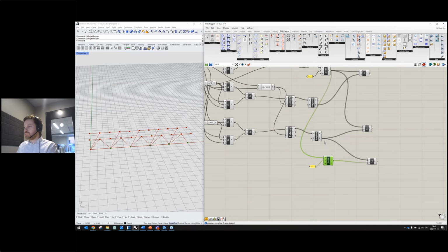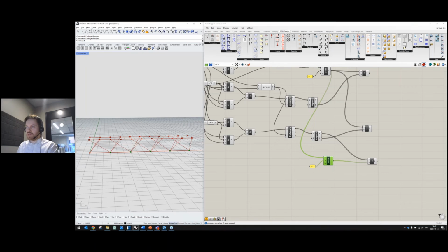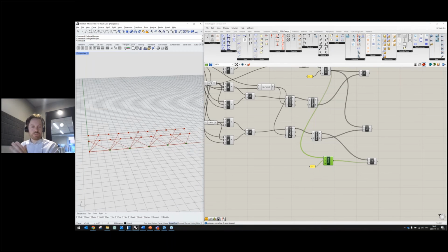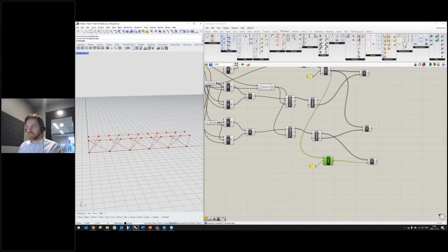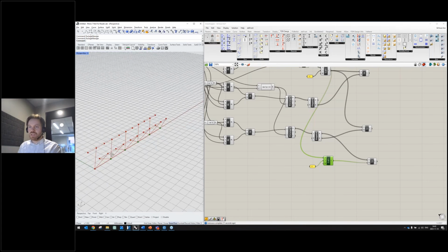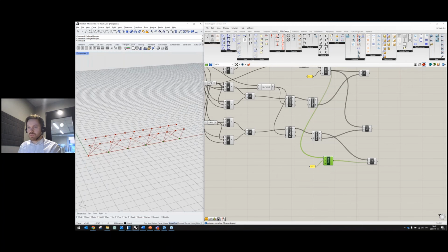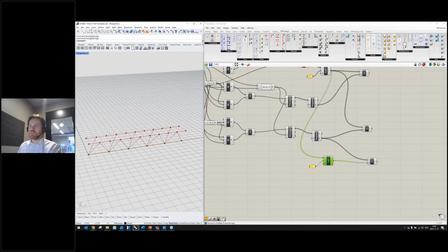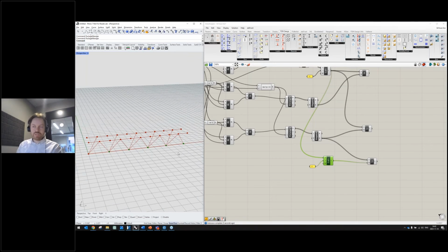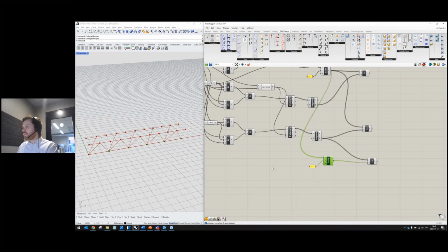points. So if you make a mistake, if you connect it the wrong way, you will get this instant feedback in the 3D view. And this is what's great about Grasshopper and Rhino. You get this instant feedback, so you can try out yourself and see what you can understand, like, okay, I'm connecting the wrong point here. I'm connecting this point, and it should be the second point, and I can find that over here at B, like this. Okay, so getting this instant visual feedback is really great when creating geometry.